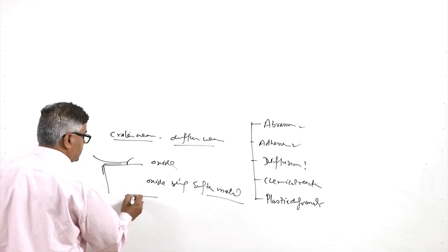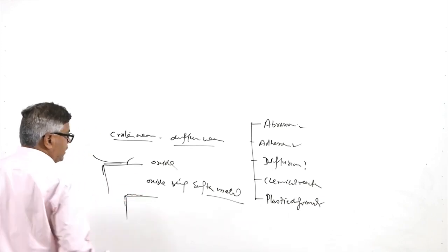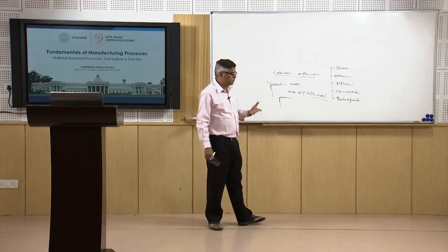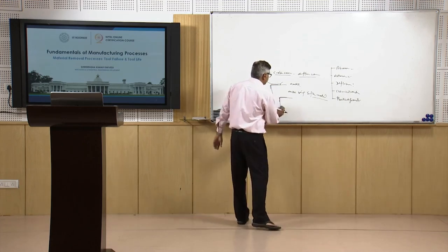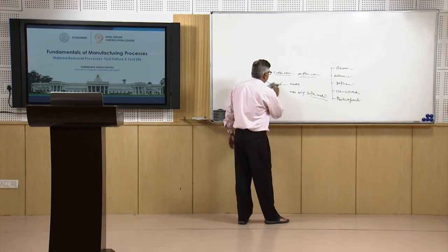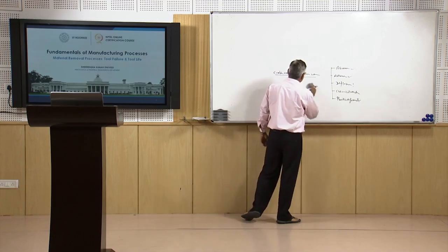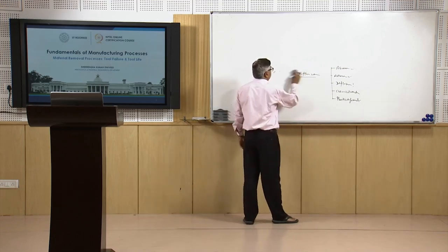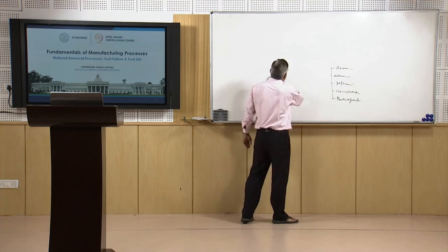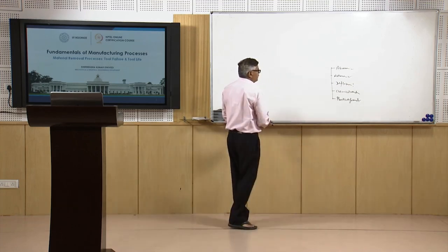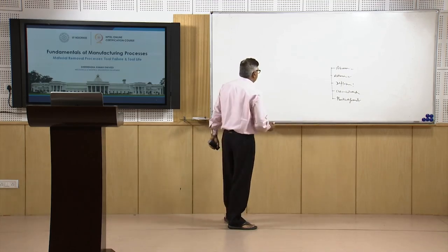So, that again will cause oxidation and removal. The formation of oxides and their removal continuously leads to the wear of the material. So, oxidation is another mechanism, and both flank as well as crater wear will be contributed by the chemical reactions, especially in the form of oxides.